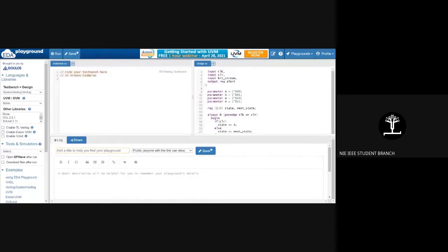This is what happens just for the states actually. So we'll talk about what happens now. Now I need another always block, which, since I'm writing a Mealy machine, should depend on both the input as well as my current state. So how do I do that?